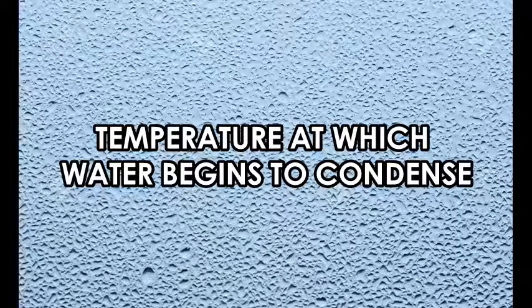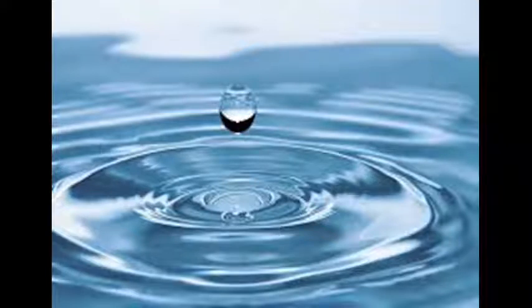Dew point is defined as the atmospheric temperature below which water droplets begin to condense and dew can form. On the average, ambient dew point is usually within 13 to 16 degrees Celsius. Below this temperature, water will condense from air. This is the same principle used by aftercoolers. If you cool down hot air, it will be forced to condense water, thereby removing water from the compressed air.